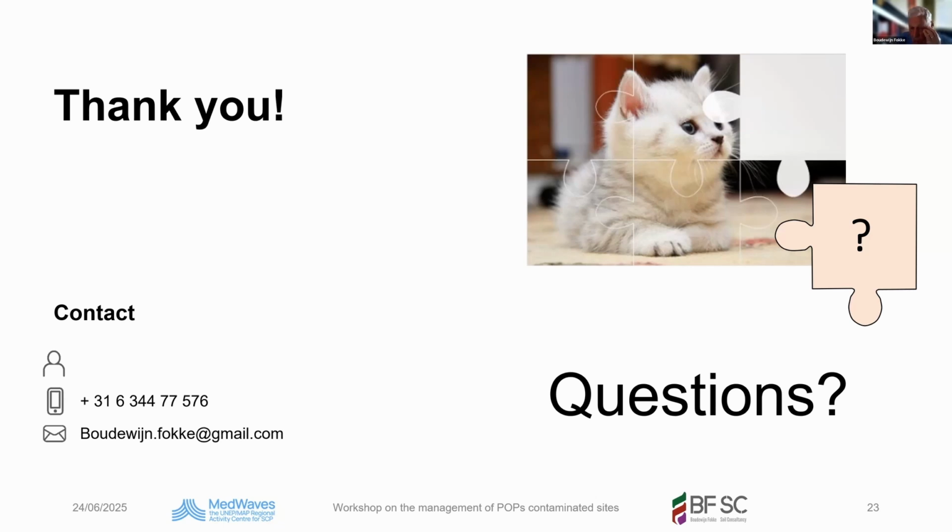To avoid that, we constructed ponds on this cap, and we allow peat to grow in these ponds, with the idea that the peat formation would take over the functionality of the artificial cap. So yes, we come across sites which cannot be remediated because of financial and technical constraints, but then the only resort is containment.